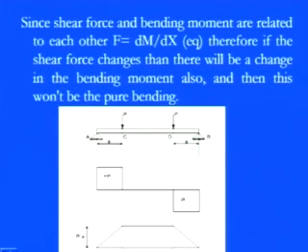So, you see here, since we know that these point loads are coming along with this particular section, in which, as I just told you, there is no shear force, dM by dx is 0, since there is no shearing. So, for that the bending moment is constant.